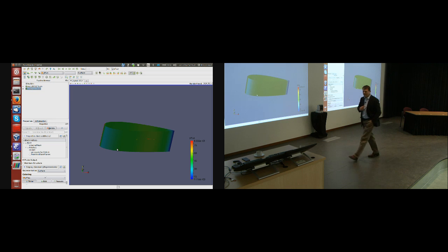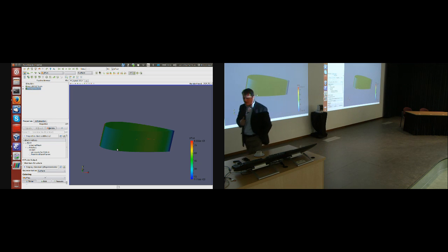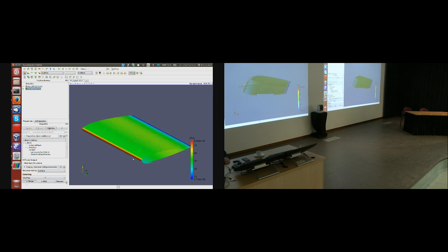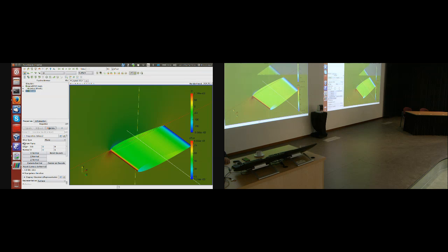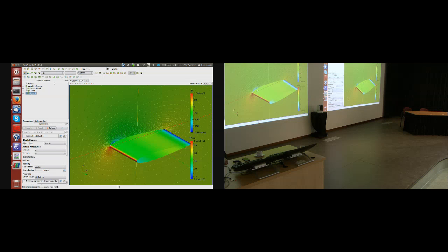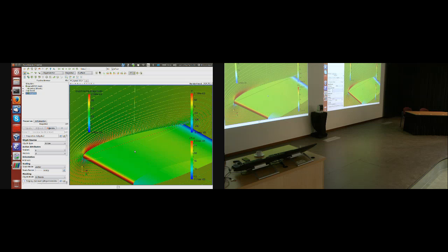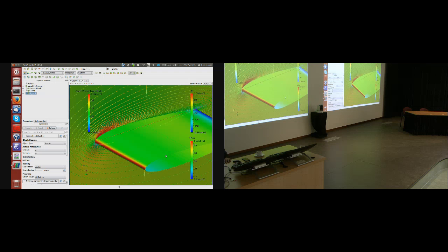Okay. The second thing that I want to do is visualize some vectors. So I'm going to jump back onto NACA 0012, do a cutting plane, Z normal, Y. I usually switch off the whole plane, because otherwise if you grab it, you move it. Okay, and again I can go scaling, all points 0.002, apply, color them with glyph vector. Okay. And here is a nice picture.